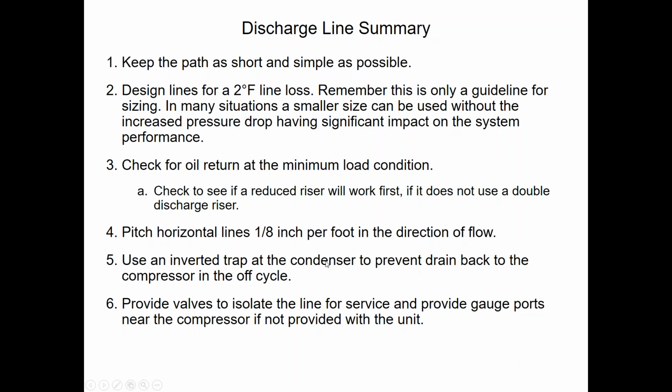Remember that when you get up around 60 ton and above, the inverted traps are not in the condensing unit, but below 60 ton, they do have inverted traps already constructed inside the condensing unit, at least on the Carriers. Now, I can't vouch for anyone else's equipment. Always check with the manufacturer. So, then isolation valves.